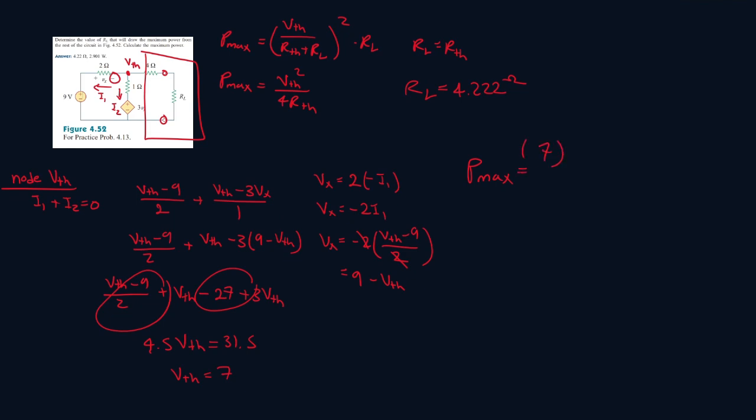It'll be 7 squared all over 4 times 4.222. And let me see what this gives me. It gives me 2.901 watts. And that's your final answer. That's the maximum power.